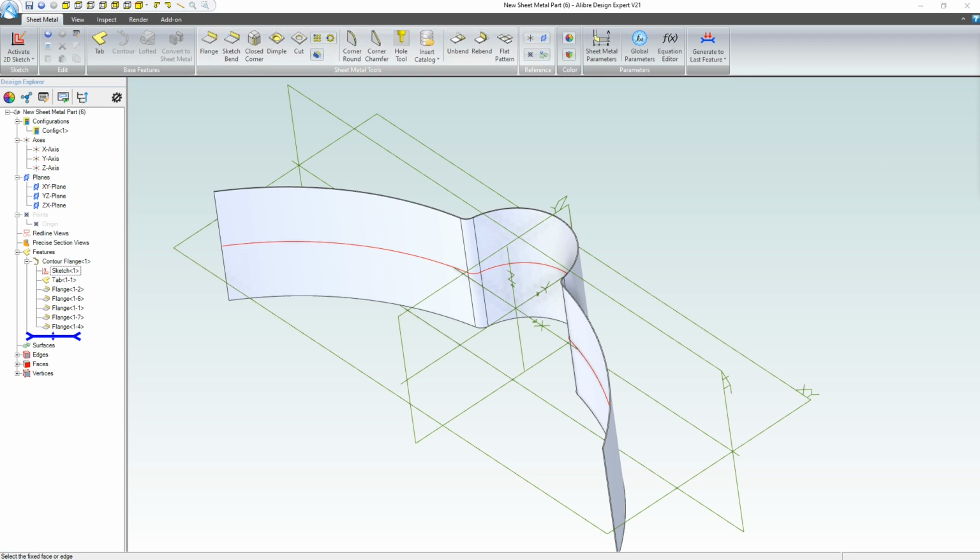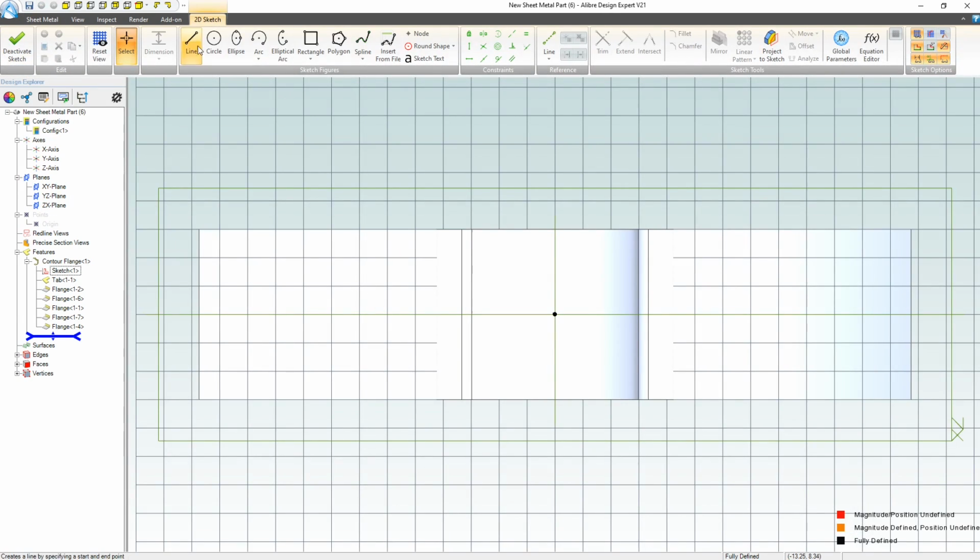So now that we can bend and unbend it, we can also add features to our sheet metal part, right? We'll do something like some circles. In fact, maybe we'll do a little tab here where I can make this, we'll give this a vertical relation right from here to this edge. Oops, I'm totally wrong though. A vertical actually needs to be coincident, right? So there we go. And we'll give that something like 1 inch is fine.